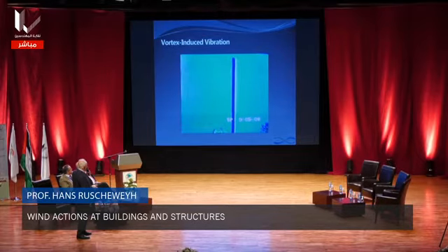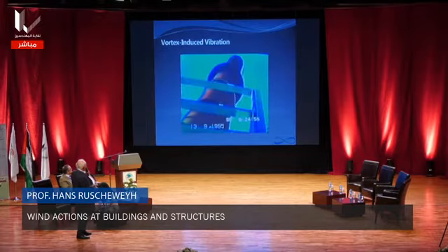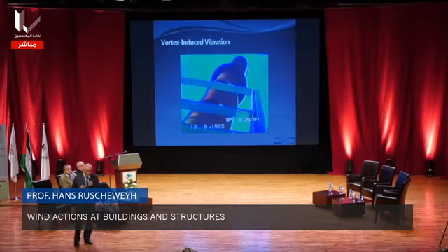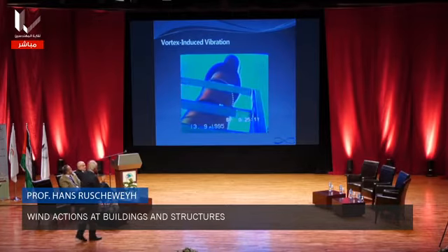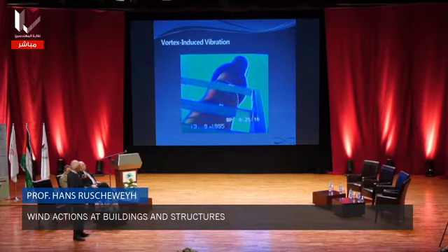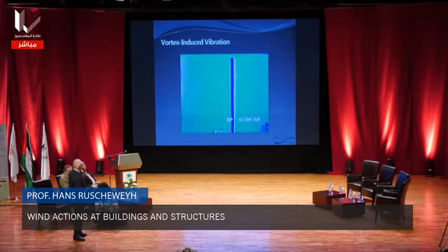And you see a big vibration, another view of the same stack. And this occurred at 7 meters per second wind. Low wind. On the Earth, you have not a feeling that there is wind, but it was vibrating. This stack later received a dynamic vibration absorber in order to reduce it.